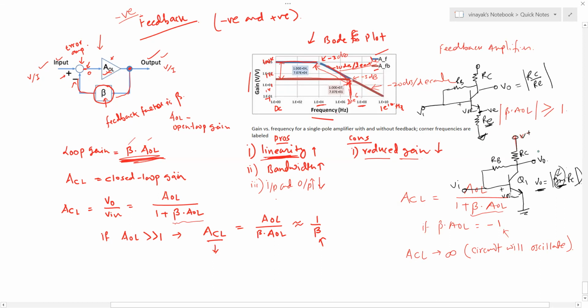So for example, let's say the transconductance of this transistor Q changes due to temperature variation. With that, GM is given as the DC current IC divided by VT, which is the thermal voltage. At room temperature, it is 25 millivolt, and the IC will then change. So if, because of the GM changes, okay, VT is fixed.